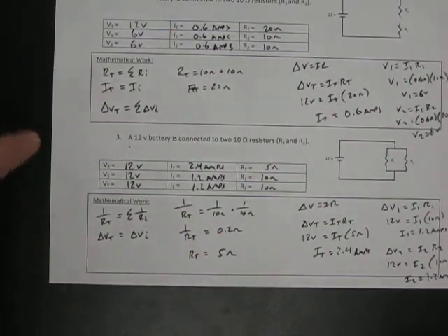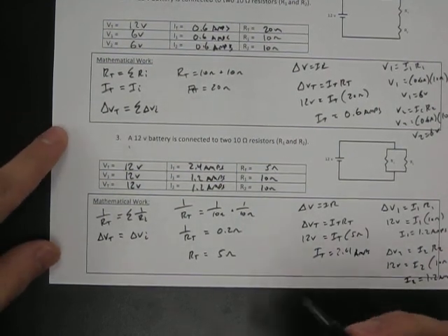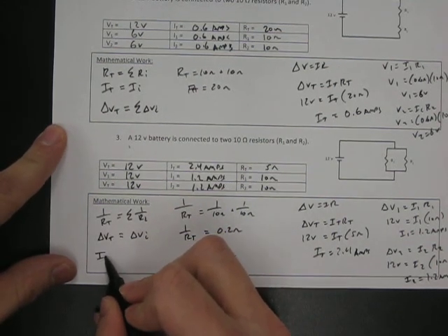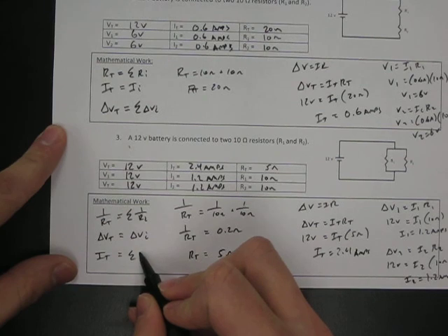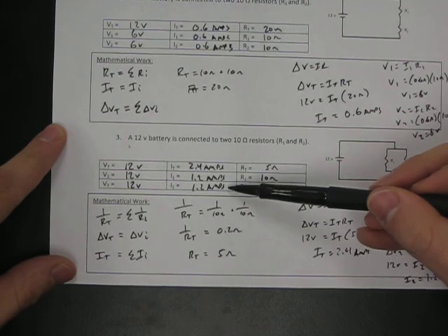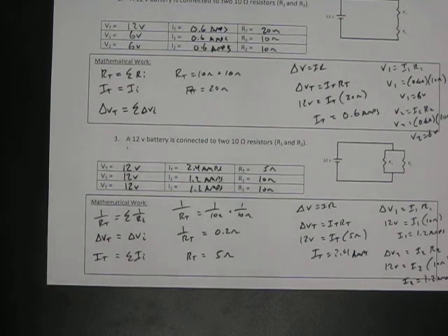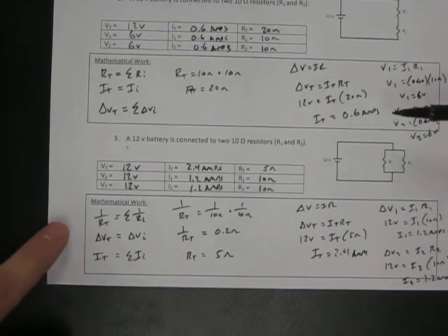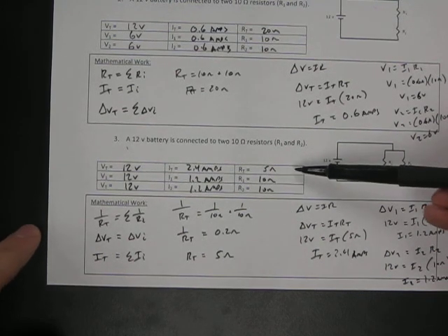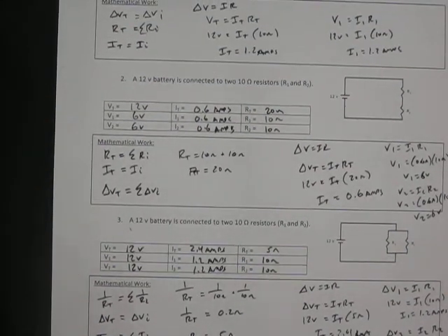Now, as you look back here at our equations that we're building, again, these shouldn't be anything new. We talked about these in our lab work. But what we learned about a parallel circuit and currents is that the total current is going to be the sum of the individual currents as you go around that circuit, which now, as you look at the data, 1.2 plus 1.2 equaling 2.4 should make sense for that equation. So let's pause and look at the totals. As you add resistors in a parallel circuit, the overall resistance goes down and the overall charge flow, or current, has gone up. So the exact opposite of what we saw up here.